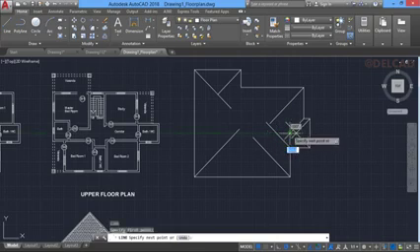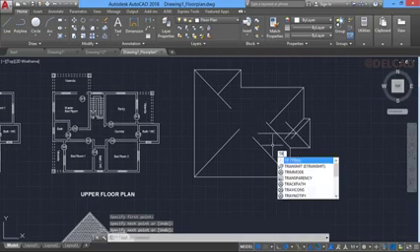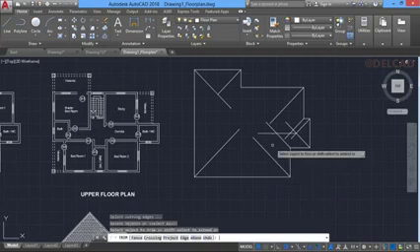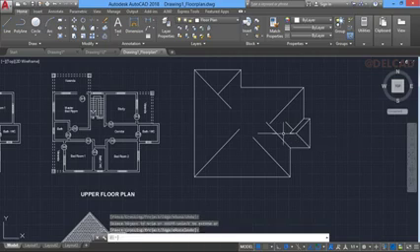So you now have to draw at this point where you have these two lines meeting, so you have to draw a line from here, a very straight line, and stop somewhere. So let's make this one a little bit neat. So use the trim command, press enter twice so we can erase some of these lines, and let it be okay, just like this. Alright, so we can erase this and erase these lines.